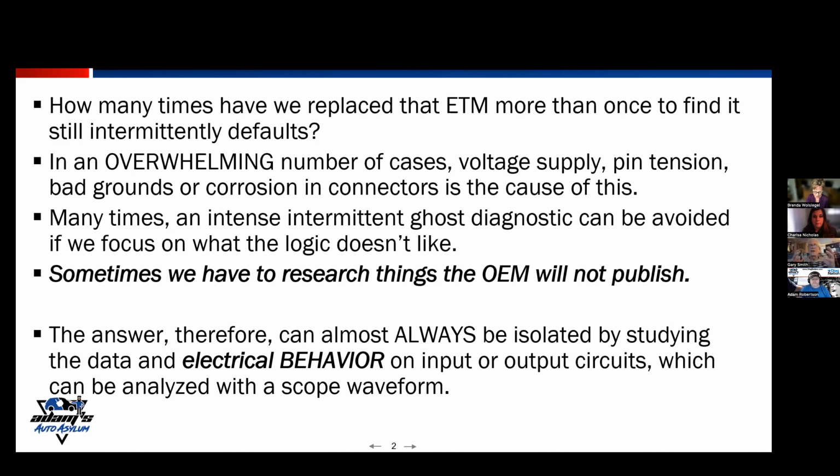In this discussion, it could be any of those motors controlled by an output driver and a module. We're finding that supply voltage side, pin tension, bad grounds, or corrosion in connectors can overwhelmingly be the cause of these faults. And we're unfortunately finding a lot of these out after good technicians have gone down a normal diagnostic path and been led to replace a modular component by the DTC chart.